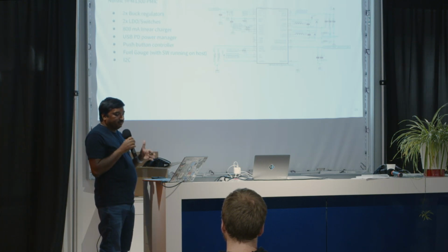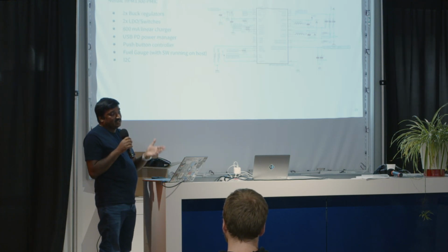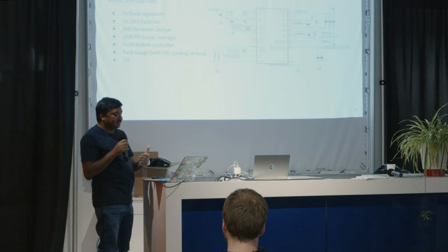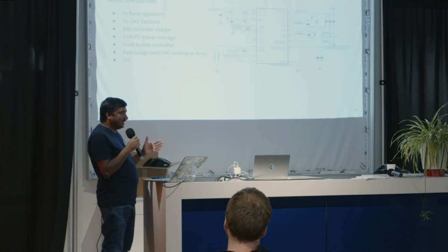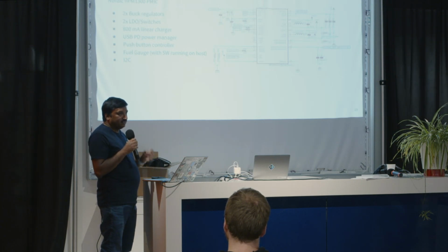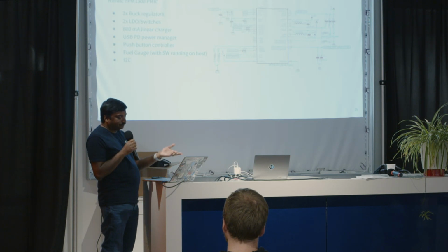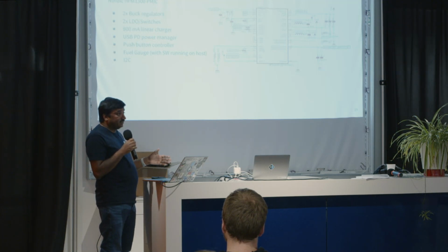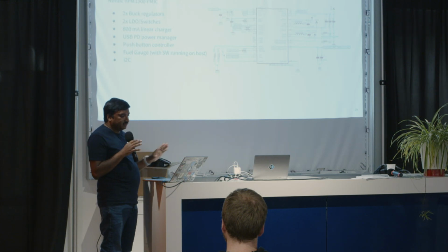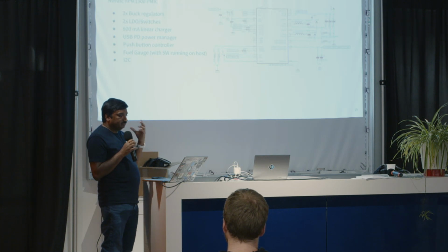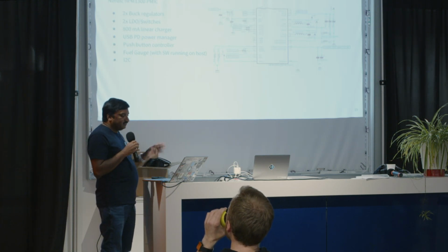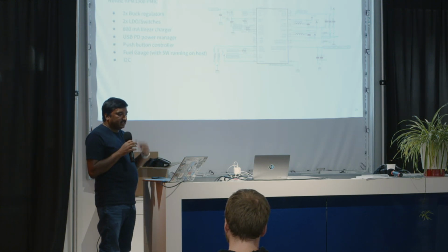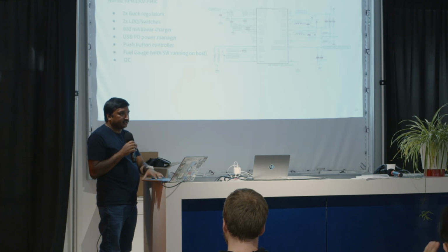We did not realize that, because every time you put a capacitor at the input and the output, and then go to the next power component, you end up losing a lot of energy. With the display turned off, and it's not optimized yet, our power consumption was almost 8 milliamps with the previous circuit, at steady state. None of the devices were on sleep or anything. But once we replaced it with this one, everything became more integrated. It immediately dropped to 2.5 milliamps. Then we started removing more capacitors and finally optimized this. Now it takes about 2 milliamps. And once it is optimized, we are expecting a few microamps.